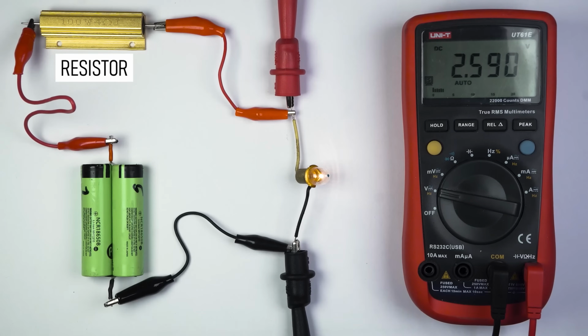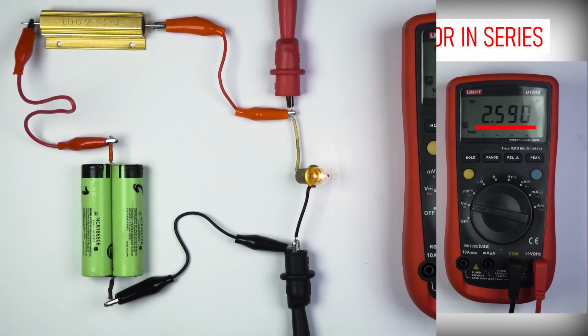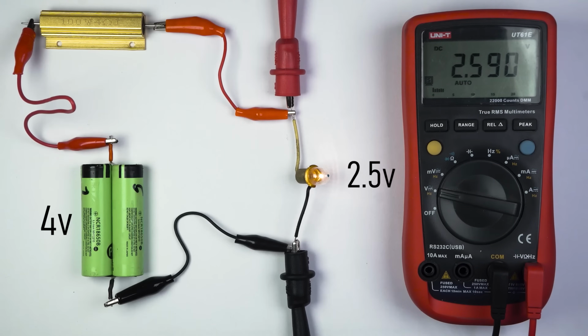The reason is that the resistor steals some of the battery's energy. As a result, the voltage on lamp number 2 is lower, while the voltage on lamp number 1 equals 4 volts, which is the battery's voltage. In electronics, this phenomenon is called voltage drop, so we can say that 0.5 volts are dropped on the resistor.